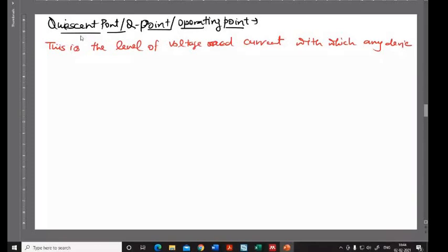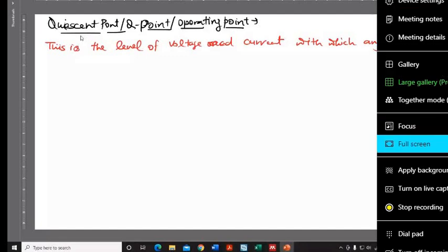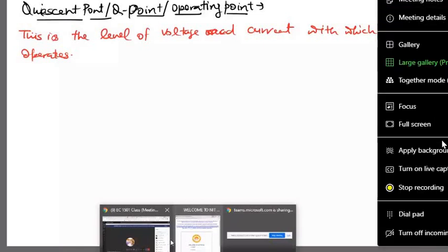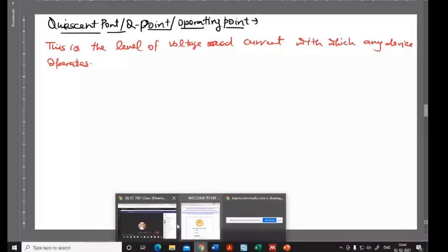And you remember what is the meaning of common emitter configuration? A common emitter configuration means we apply the input voltage VBE here, and the voltage at the output terminal is VCE. This is plus minus, and this is minus plus, for NPN. So this is the CE configuration, and these are the characteristics where I'm going.